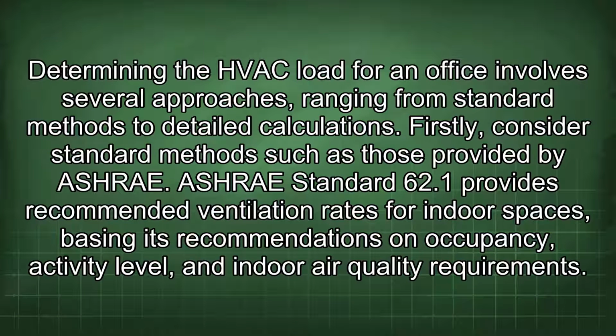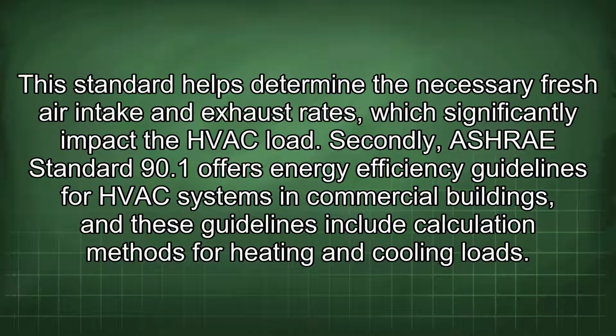Determining the HVAC load for an office involves several approaches, ranging from standard methods to detailed calculations. Firstly, consider standard methods such as those provided by ASHRAE. ASHRAE Standard 62.1 provides recommended ventilation rates for indoor spaces, basing its recommendations on occupancy, activity level, and indoor air quality requirements. This standard helps determine the necessary fresh air intake and exhaust rates, which significantly impact the HVAC load.